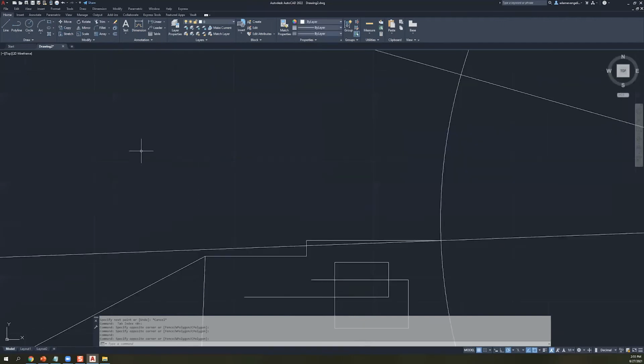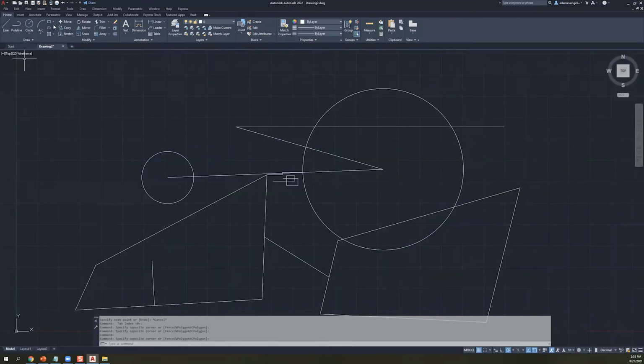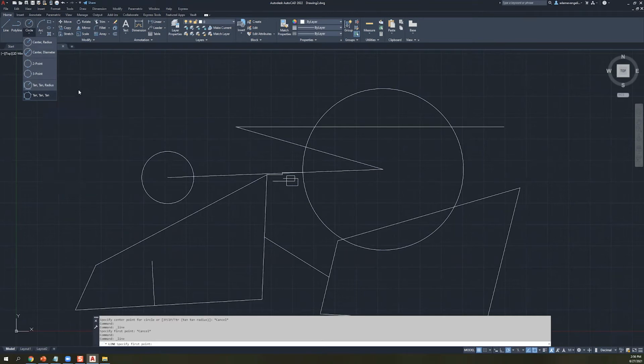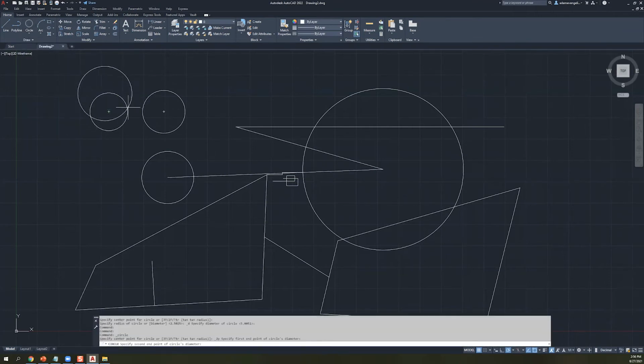In addition to everything here, I kind of just glossed over circles and lines and squares, but circles come with a variety of different solutions as well. There's only one way to make a line in this case, but under the circle option, there's multiples. You could define a circle using center radius, center diameter, 2-point, 3-point, tangent tangent radius, all sorts of different ways to use circles. I hope these are pretty self-explanatory, but center radius takes a radius, for example, center diameter takes a diameter instead. Similarly, 2-point does that. You can see the way the geometry moves and is a bit more dynamic. It's interesting stuff.